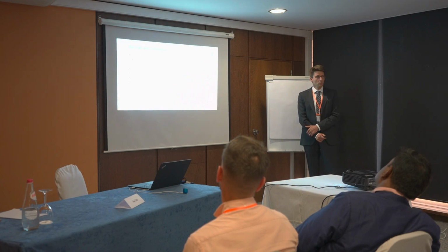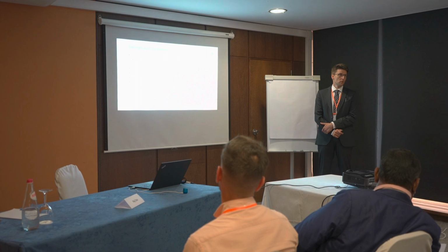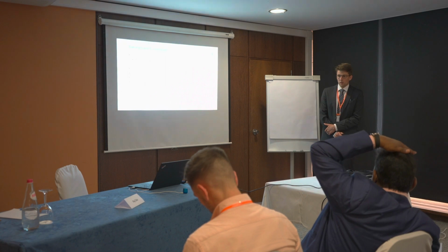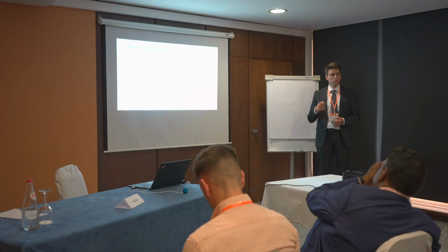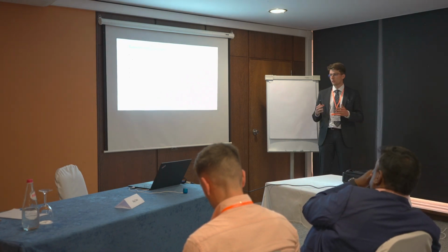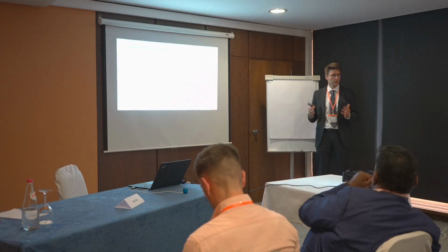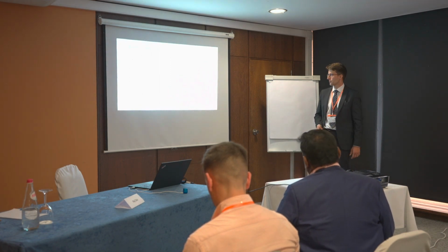Then, when you have an optical extensometer, you need only one step for the calibration. You do not have to rearrange the bars. And it's also possible to perform the calibration during an actual test. And another thing is you can check the calibration each time you perform a test. So maybe you can check if the instrumentation of the bars is still intact. You can detect a degradation of the instrumentation.